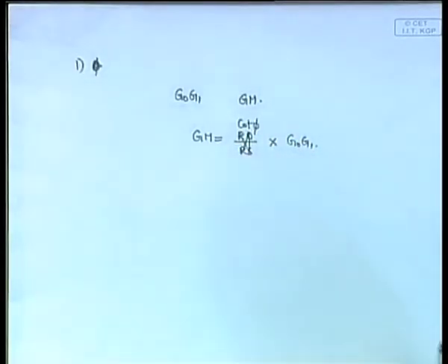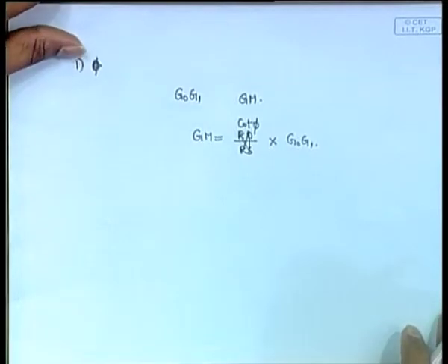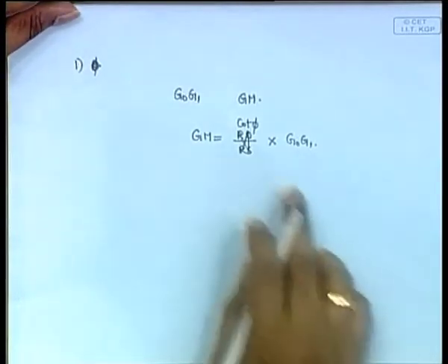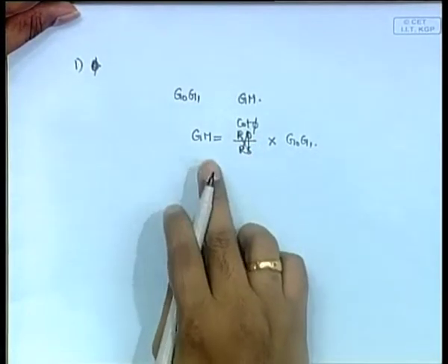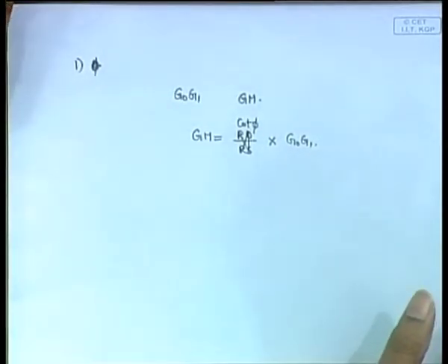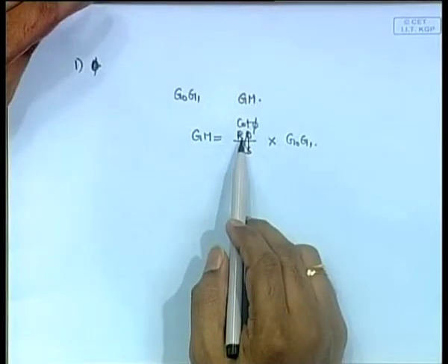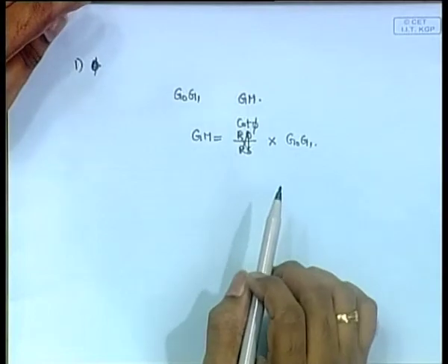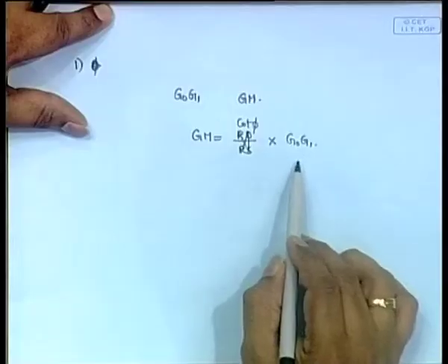So, this is the formula. If you have to find your phi, this is the expression. Please remember this expression. The question will definitely have something to do with the derivation of the inclining test, because it is a very important thing. So that method of derivation and the experiment is to be remembered definitely, and this final expression you just keep by heart: GM is equal to cot phi into G0G1.